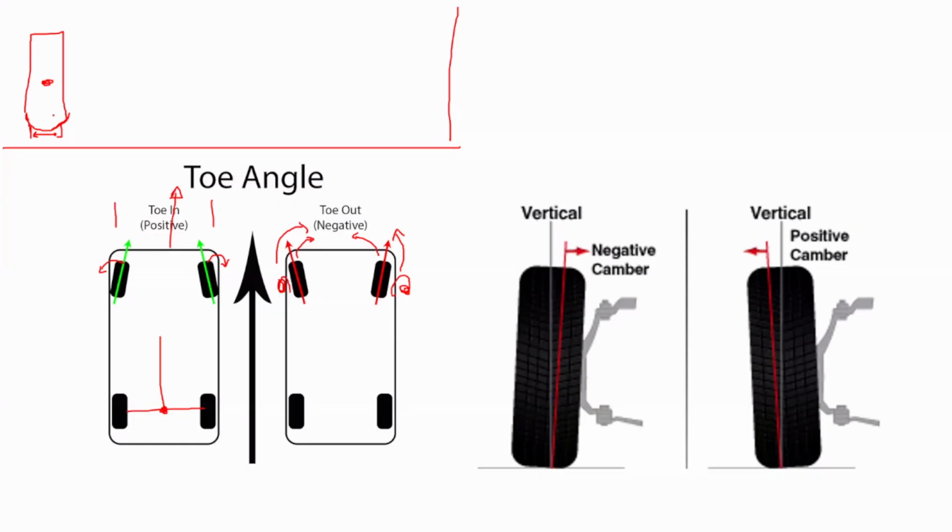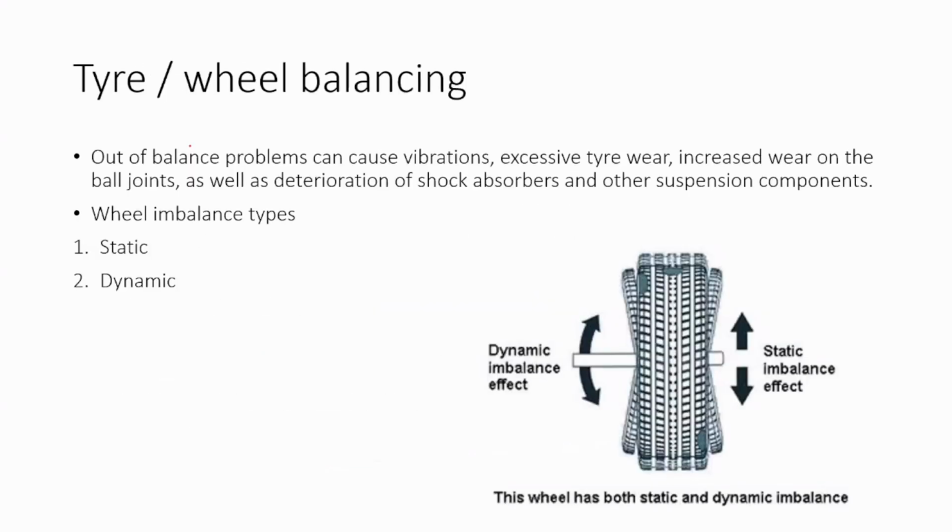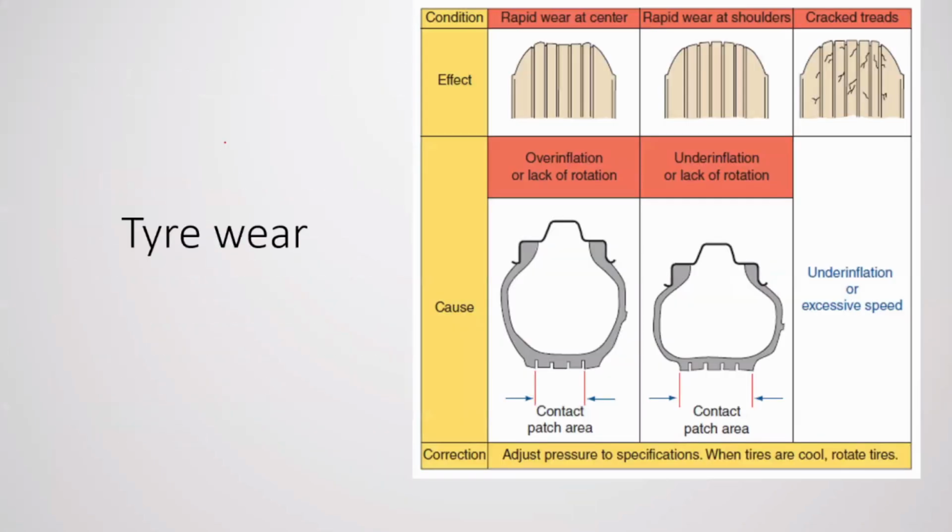Surely the tires will be stuck inside the sand, so if you see that your terrain has some sand conditions, for a beach or desert, first you need to reduce the tire pressure, right? So once you reduce the tire pressure, what happens? So let's go back to the reduced tire pressure section.